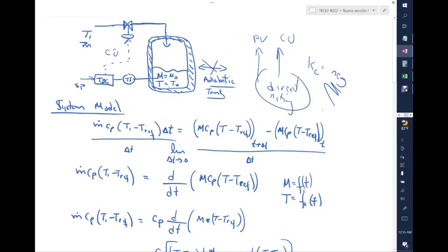So that's why you have to be very careful, and that's why we are also using a proportional controller, not a proportional integral controller, not a PI controller, but only a P controller. A PI will drop below, and that's the end of it. It would not work. A PI controller is not good for this type of scenario. We are using a proportional controller to get this job done.